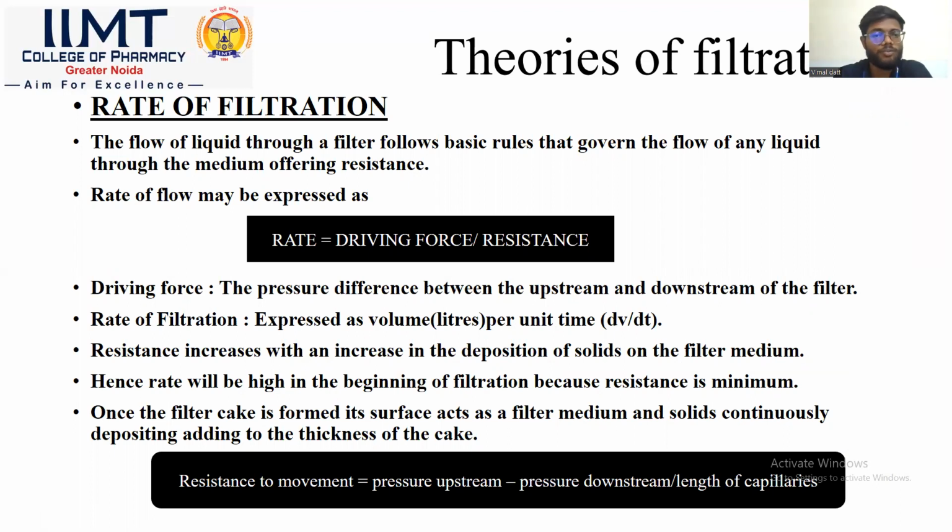Second, rate of flow may be expressed as rate is equal to driving force divided by resistance. So what is driving force? Driving force is the pressure difference between the upstream and downstream of the filter. Second is rate of filtration, expressed as volume in liters per unit time, dV by dt.